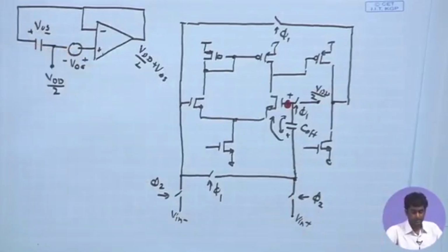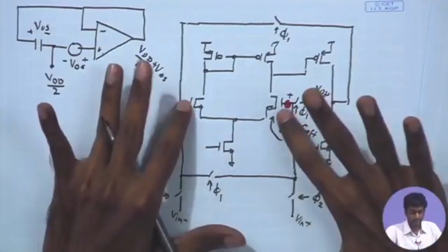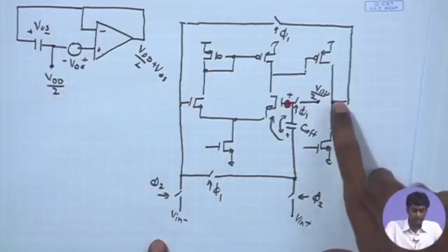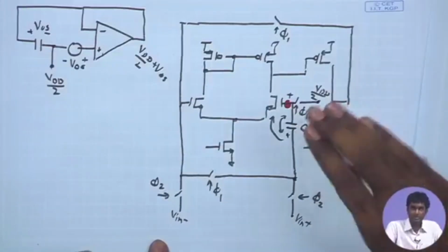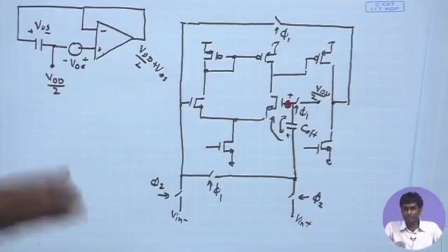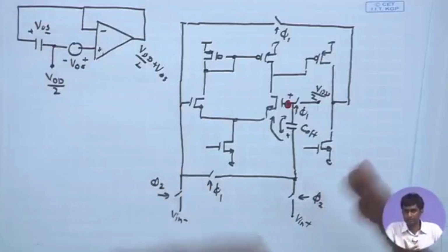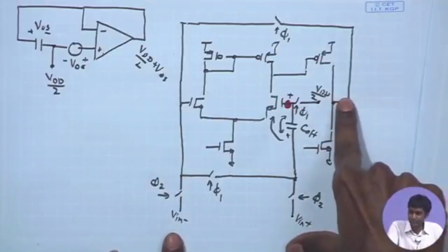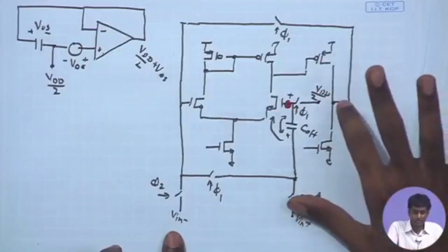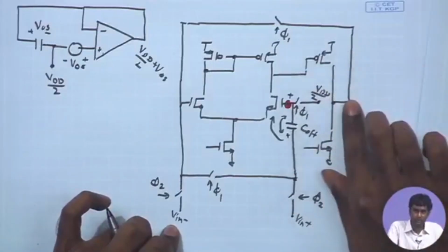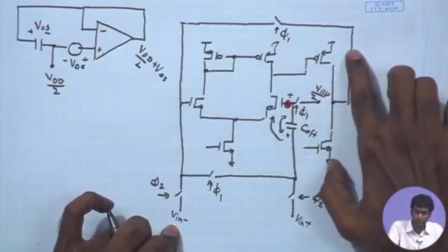So, this relates to the DC biasing. We are not biasing the input for any DC. Of course, we have discussed that in a comparator operation we need not be concerned about biasing the output also, because ultimately we are concerned with only high or low levels. So, for the differential amplifier operation in the front end, we have discussed the common mode feedback, and we have discussed a couple of strategies, stabilization techniques, but here we are not even considering the output DC point, and because the output will not be stable at one DC bias point, it is going to be nonlinear operation, either the output is supposed to be close to VDD or ground.